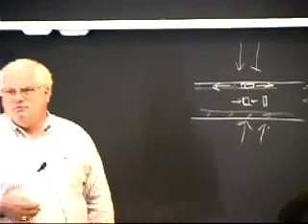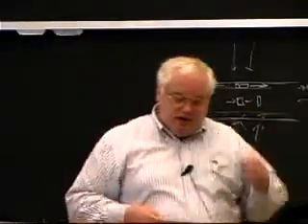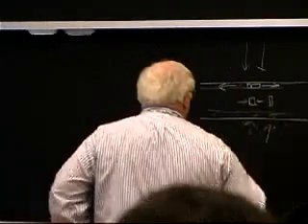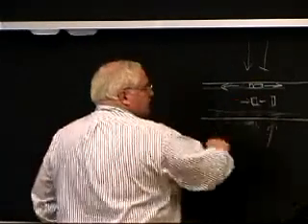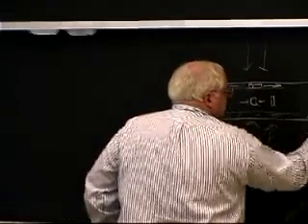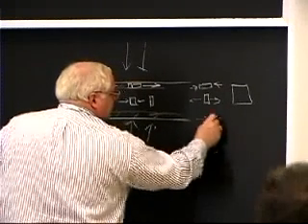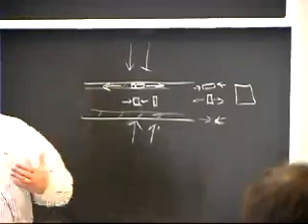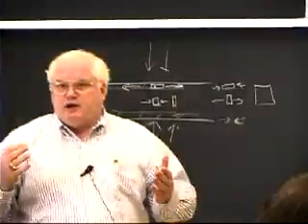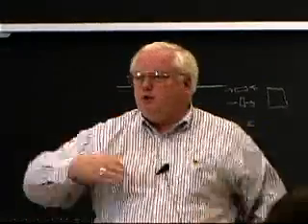So that's for glass, and that's called tempering of glass. You're changing the way it cools. So you cool this faster than this, and you end up with the compressive surface stresses when you're all done. And compressive surface stresses are good because I have to overcome the compressive stress on the surface in bending before the glass is going to break.